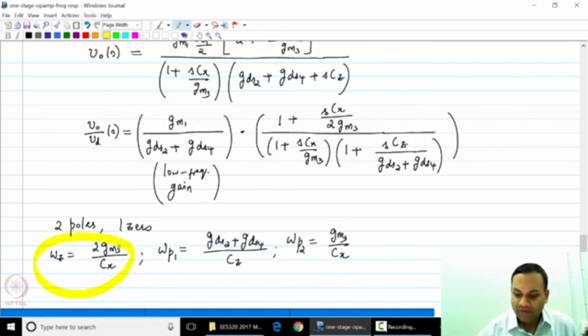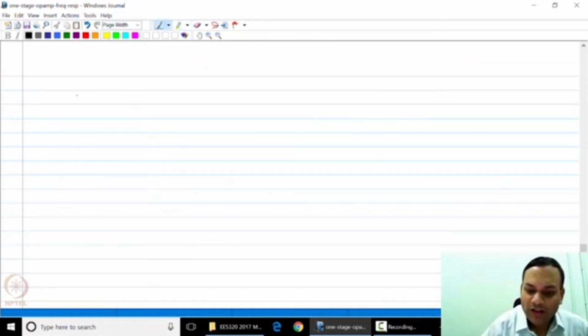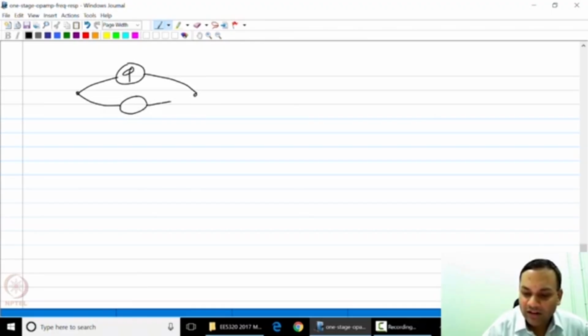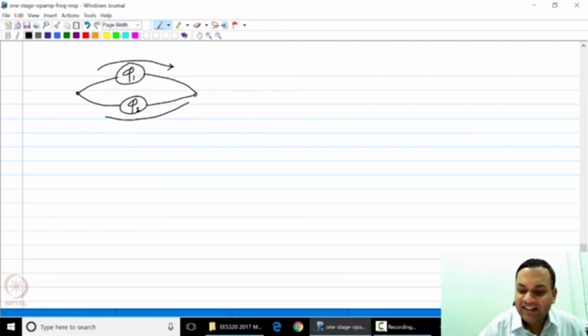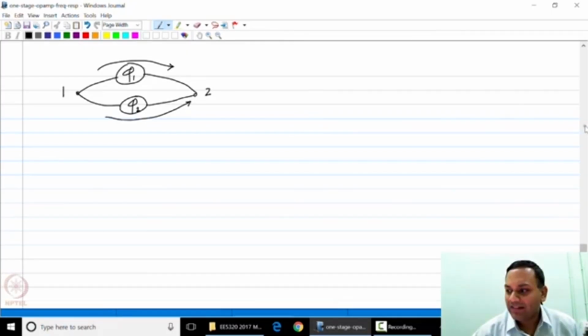and first of all you need to ask yourself why you see a zero. Normally you will find that you see a zero when you look at the transfer function between two paths. If you see a relative phase shift, especially a frequency dependent phase shift between the two paths, you will normally see a zero. So that through the two paths the signal adds destructively at a particular frequency. Do we have these two paths in the system?